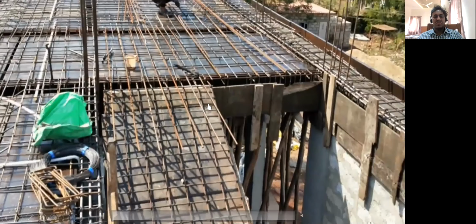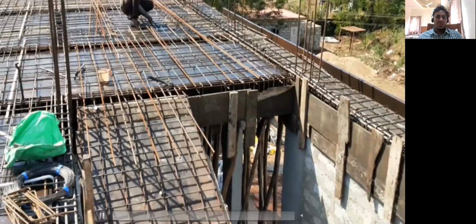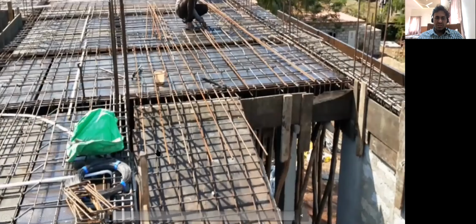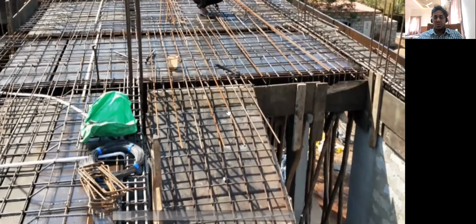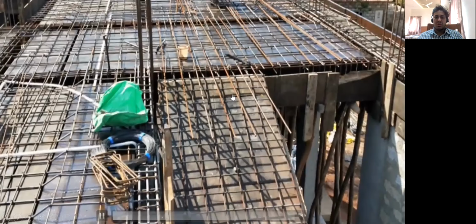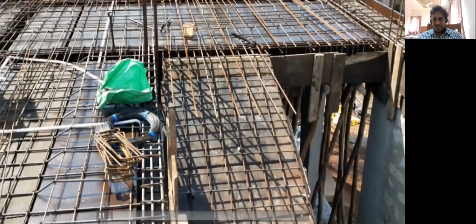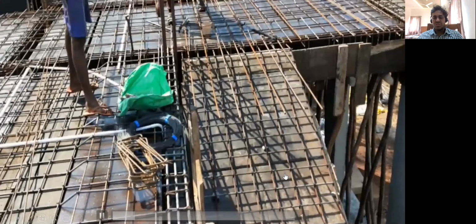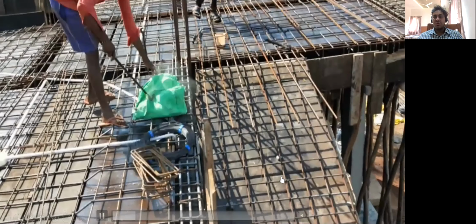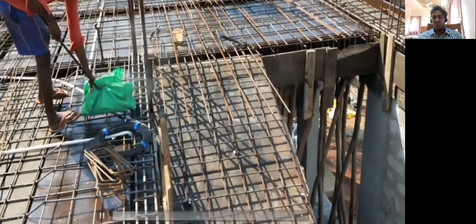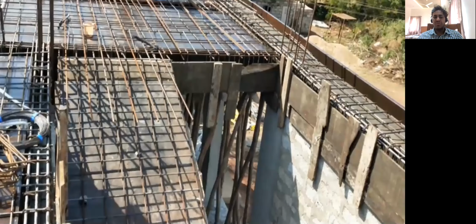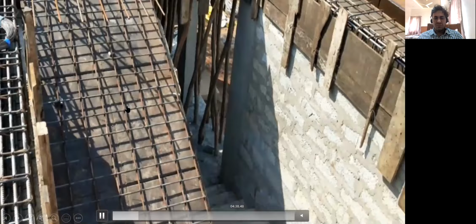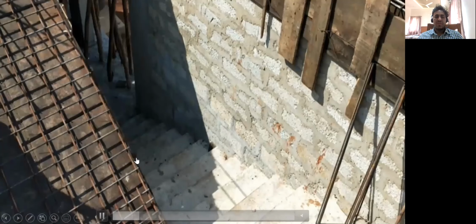So this is how it is going to look. This bar they are going to crank and bring it here. These are my top bar. Since your negative bending moment is more, you are going to put more reinforcement here. Similarly, in this support also you are going to put more reinforcement. Whereas in the center portion you have only the bottom reinforcement, because in the center the sagging moment is more. There is no negative bending moment. But near the support and here we have more negative bending moment.